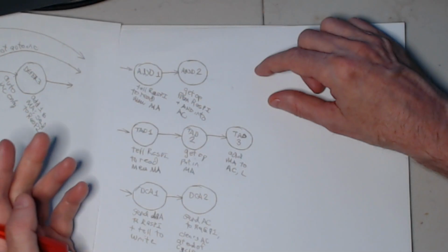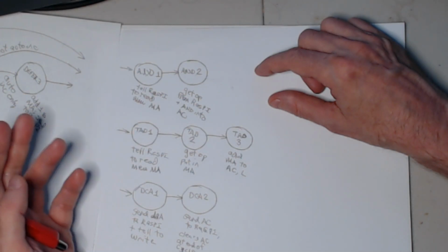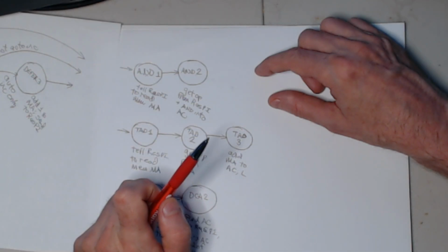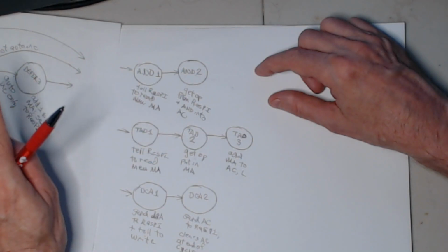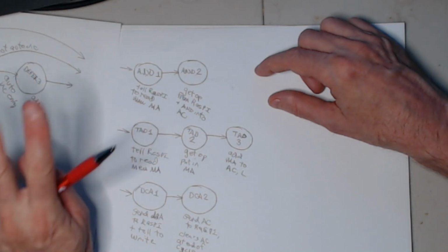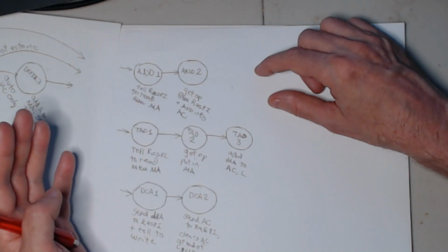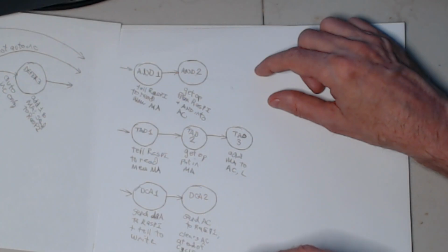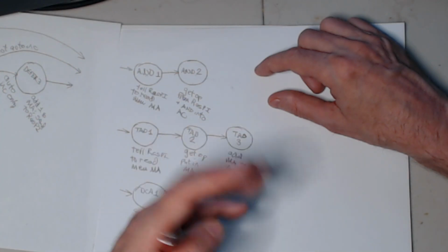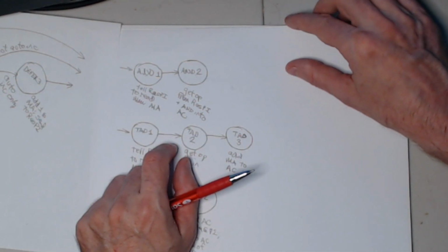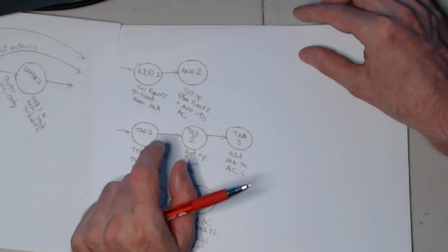JMS takes 3 cycles. The first 2 of them are writing the old program counter to memory, so that's a write operation that takes 2 clock cycles. And then the 3rd one is incrementing the memory address register and plunking it into the program counter. So that's how JMS works.